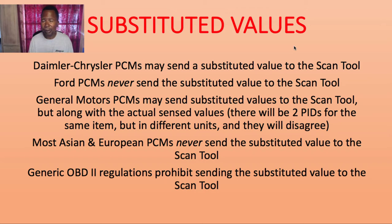And the reason that the numbers aren't moving is because it's following the TPS. And using the TPS input as a substitute number, then substituting a number for the mass airflow just to get the car going. That's called a substitute value.